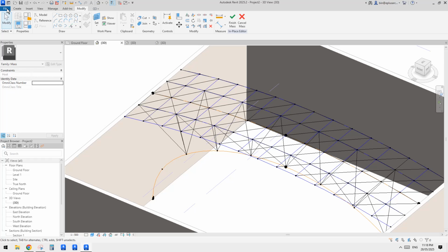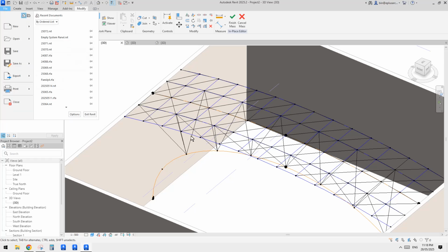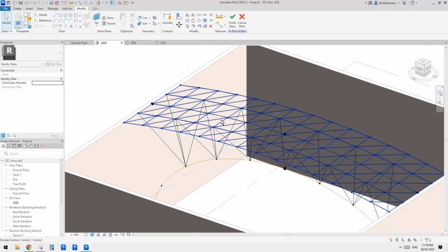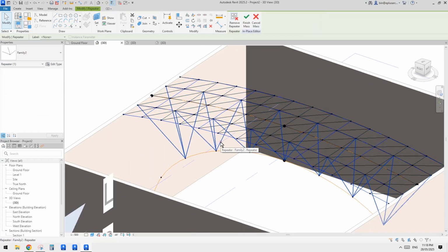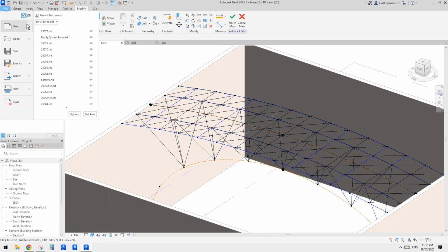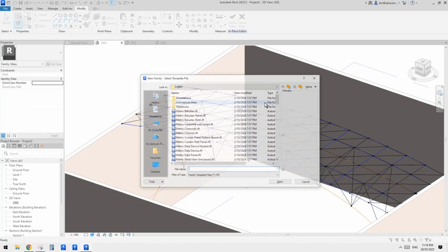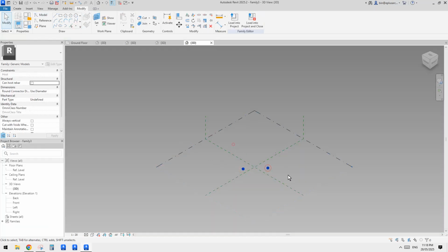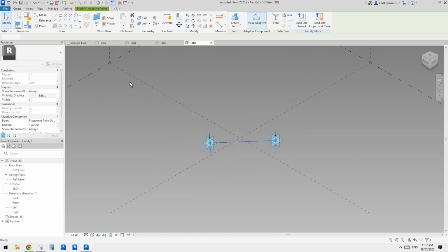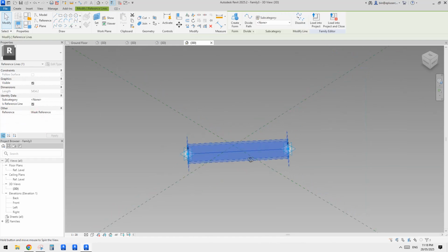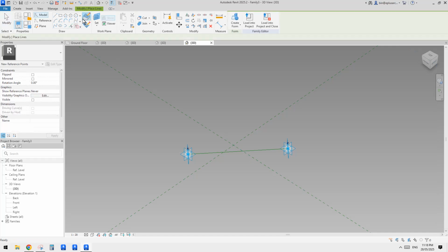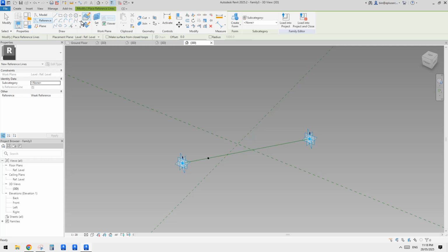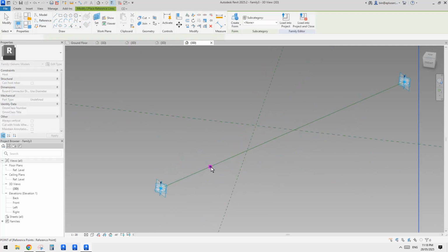So now I'm going to create a family for all these framing, and then we can use that in this pattern based family and also in this adaptive family. So let's do it. We need another adaptive family. In this family we need 2 points, make them adaptive, create a spline through point, and make it reference line. So place a point, use draw on face onto this, and create a reference circle, draw over plane, set over plane, and place it here.